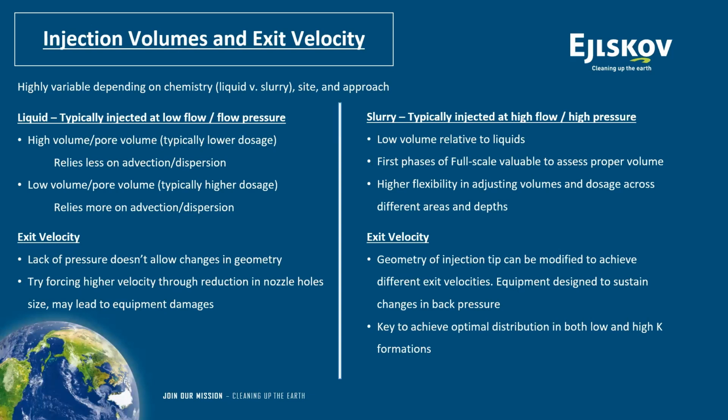And so we try and match up that velocity with the geology. For example, it's somewhat counterintuitive. You have to have a higher exit velocity when you are in something like fine or medium coarse sand, because the sand wants to really filter out the solids. And so you actually have to put more energy into a sand than you do a clay whenever you're dealing with slurries, which is somewhat counterintuitive. And obviously, from a safety aspect, you want to make sure that your equipment is designed to handle whatever your maximum pump pressure is, plus a safety factor.